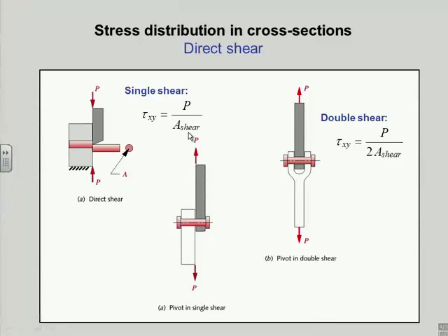So this is a very crude approximation, because if I looked at the instantaneous shear stresses as it goes through, I would see some sort of a shaped curve that wouldn't be a constant value. So I'm averaging everything here. And the argument there as to why that's legitimate and useful is that in respect to failure, until I've gotten all the way through, I don't really have a failure. So I have to disrupt the entire cross-sectional area before it breaks in two, right?